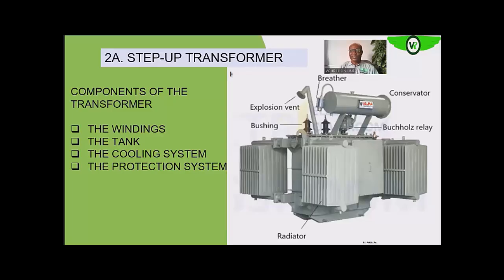As the oil molecule is disintegrated, hydrogen is formed, and that hydrogen moves up naturally and starts to pressurize the tank. So if the rate at which that hydrogen is formed is higher than the rate at which it is getting out somehow, maybe through the breather, you will see that the pressure in the tank will build up to a stage that it can cause explosion of the tank.